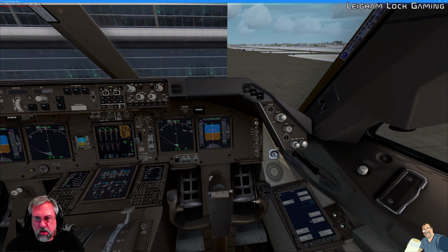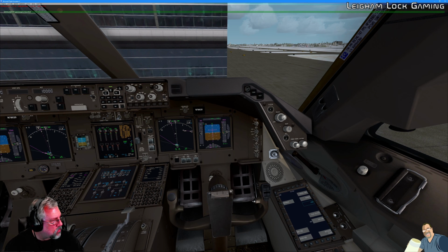The controls down here, our source selection controls, are pretty much all in the correct position to begin with on the first officer side. Pretty much flight director is on the right. Nav, he's using the right FMC. What do they call it? The EFIS ECAS interface unit. The EIU selector should be in auto, along with the IRS is set to auto, and the air data information is set to auto as well. All standard settings. Those are verified.